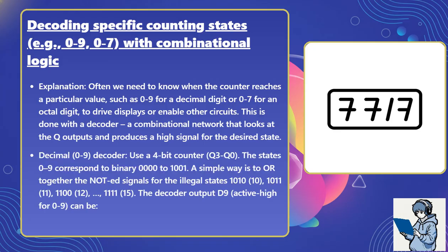Use a 4-bit counter, Q3 to Q0. The states 0 to 9 correspond to binary 0000 to 1001. A simple way is to OR together the NOT-ed signals for the illegal states 1010, 1011, 1100, and so on up to 1111. The decoder output D9, active high for 0 to 9, can be D9 equals not (Q3 dot not Q2 dot Q1 dot not Q0) dot not (Q3 dot not Q2 dot Q1 dot Q0) dot ...